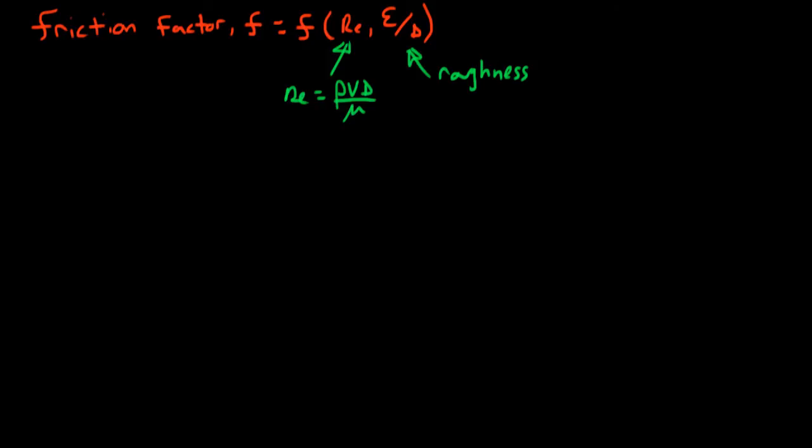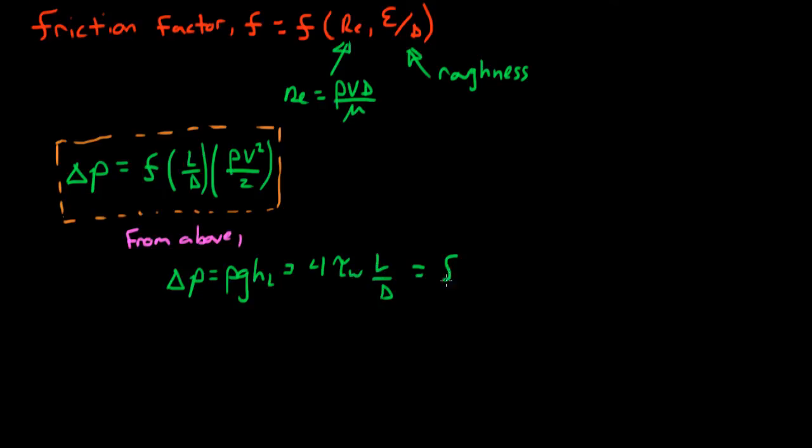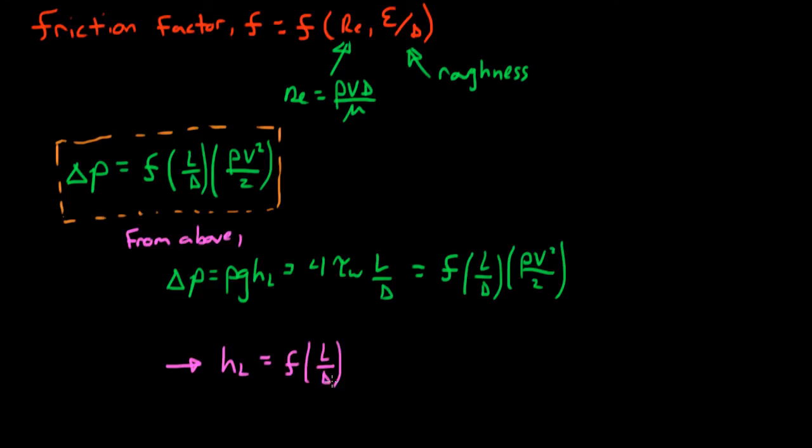The logic that leads to the friction factor definition is similar to the development of the Reynolds number. The friction factor is defined using the change in pressure is equal to the friction factor f times the length divided by the diameter times 1/2 density times velocity squared. Once we have a friction factor, we can return to the definition of friction factor to compute the head loss, which can then be used in the energy balance that we derived above. We have the head loss equal to the friction factor times L over d times the velocity squared divided by 2 times the acceleration due to gravity.